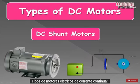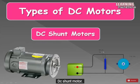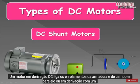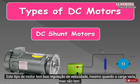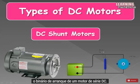Types of DC electric motors. There are four types of DC motors explained below. DC shunt motor. A shunt DC motor connects the armature and field windings in parallel, or shunt, with a common DC power source. This type of motor has good speed regulation even as the load varies, but does not have the starting torque of a series DC motor.